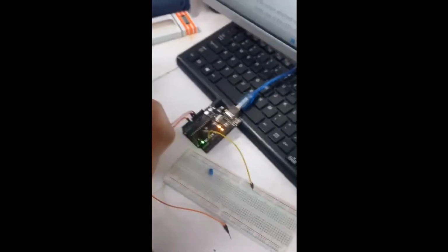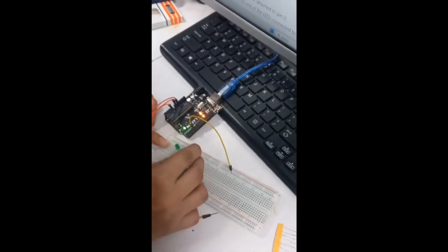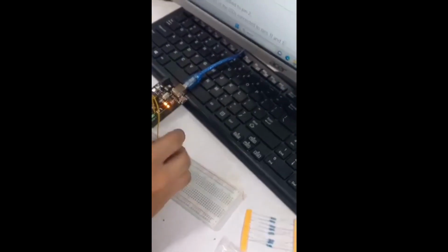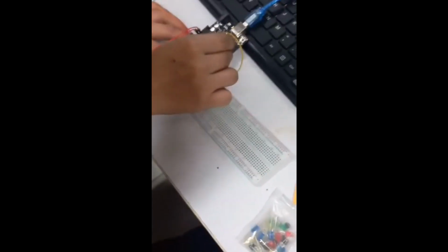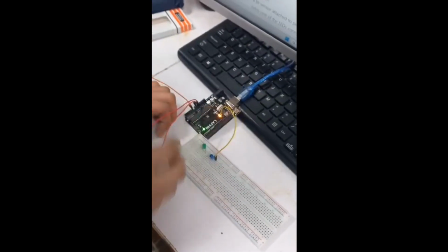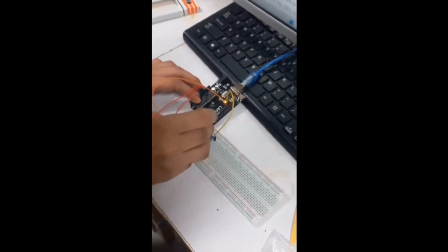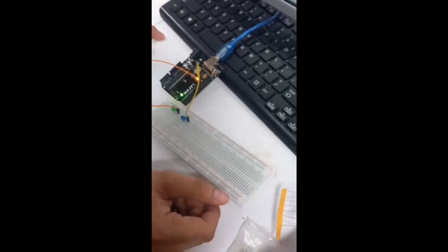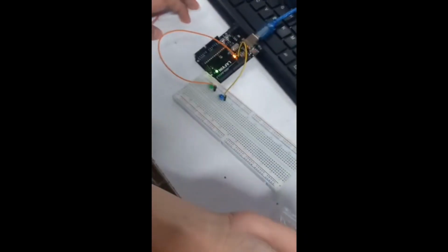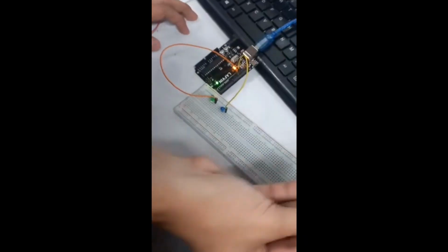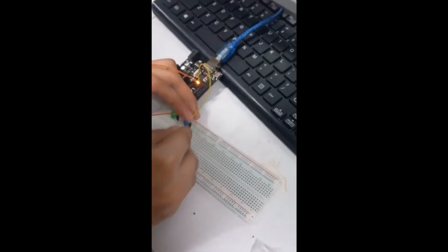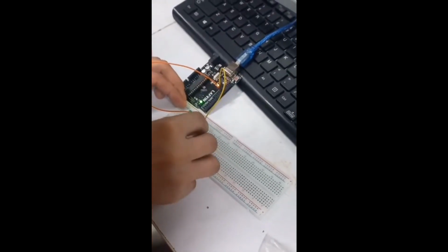Wiring wizardry, connecting the sensor. Follow the wiring diagram. Ensure you have the correct one to create the following connections. Tilt sensor's output pin to a digital input pin specified in the code. LEDs' anodes to digital pins 11 and 12, cathodes to ground via resistors.